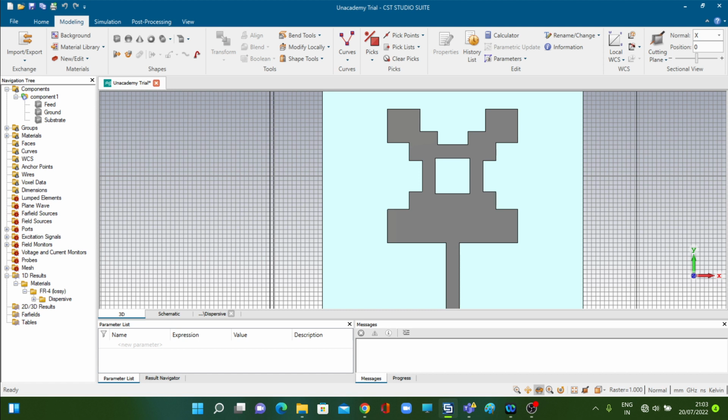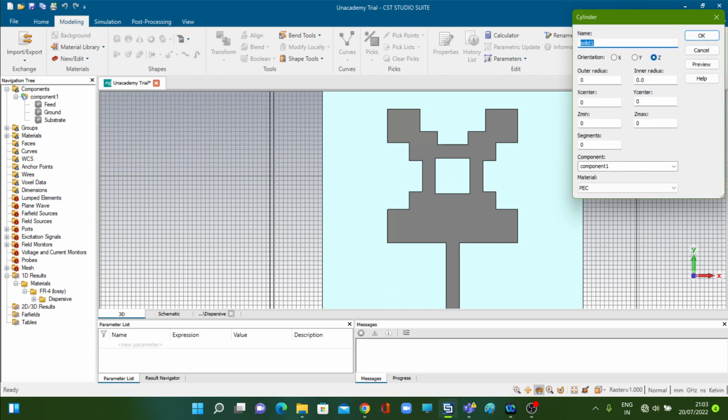Now, in order to generate this annular dielectric resonator, we will start creating the resonator from the beginning once again. So how we did that? Cylinder, select, escape, give the same name, DR cylinder annular. Outer radius was 6 units, we keep it as 6.